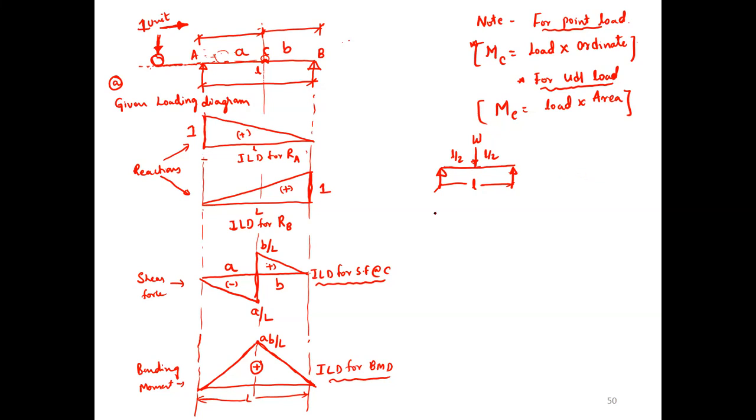I am going to compute the moment basically. That's why, which standard diagram do I have to consider for moment? Which is the standard chart for moment? ILD for BMD. That is the standard. So you just take the standard chart below here. This will not alter.